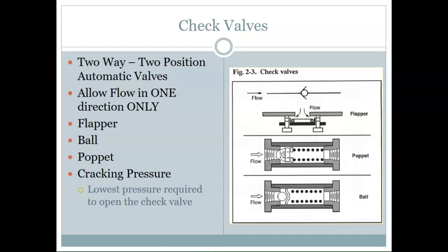So you have what's called the cracking pressure with a check valve. What that means is that it's the lowest pressure required to open that valve. That's cracking pressure in general. It's not just applied to check valves. It applies to all valves.